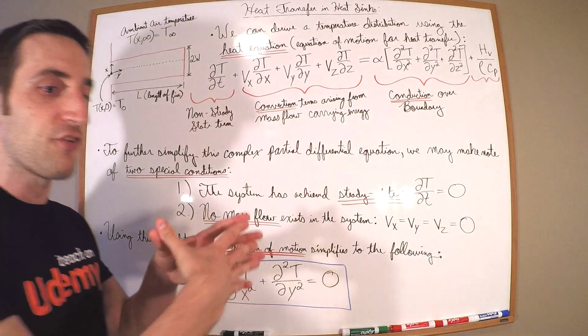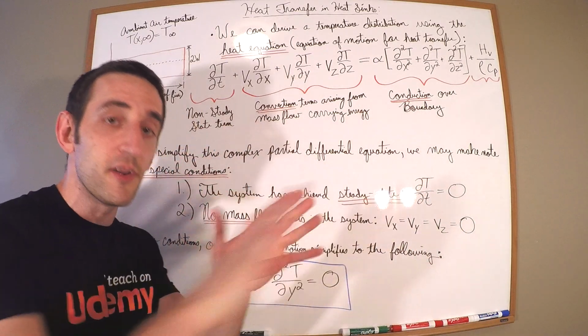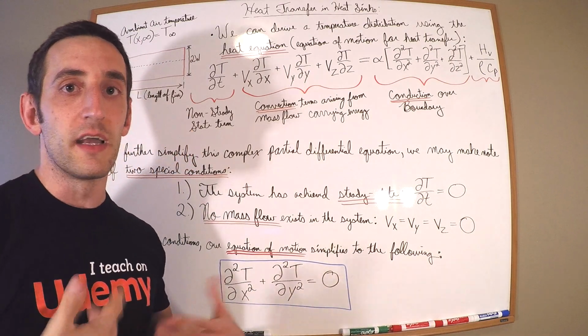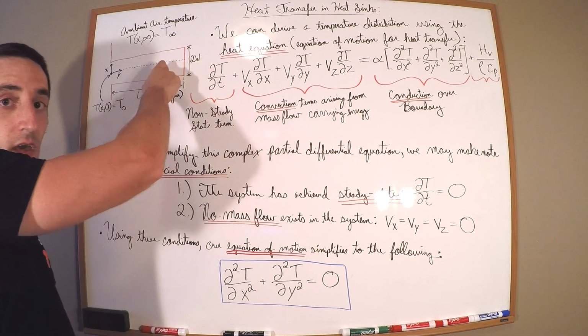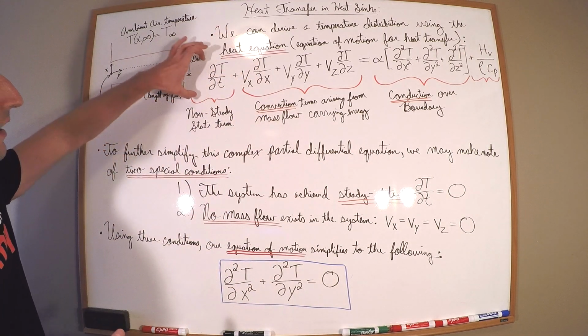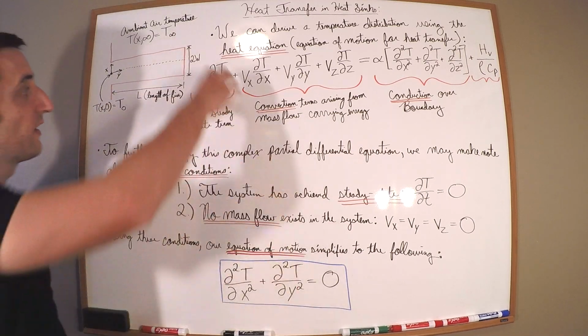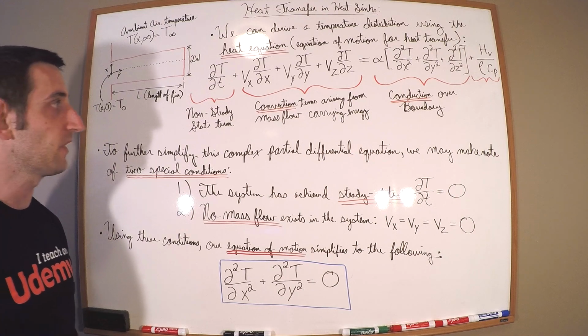So eventually that transition phase is going to be knocked out, and then we're going to have a steady flow of heat, a steady flow of conduction and convection, and at any point within this, that temperature will not change with time, okay? So initially, in that transition phase, we need to account for a non-steady state term, which is this dT/dt, okay?